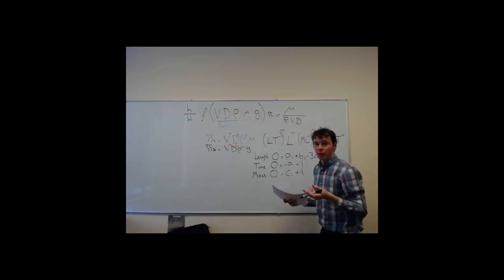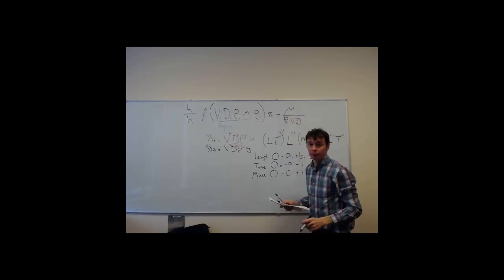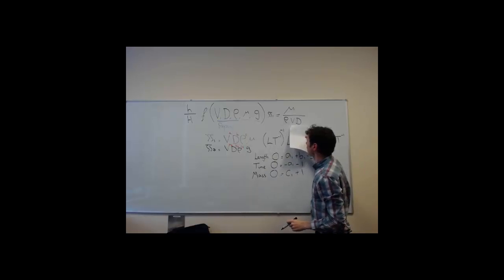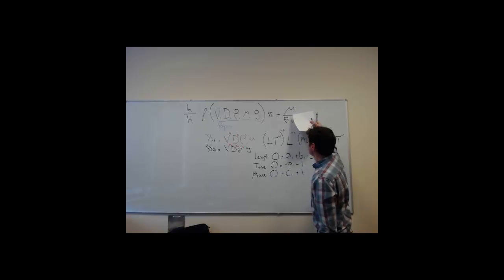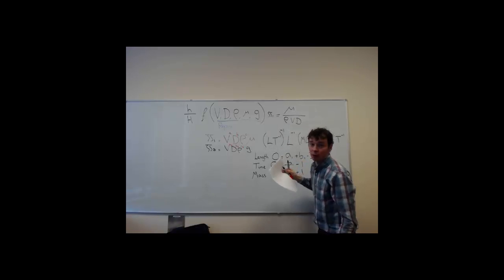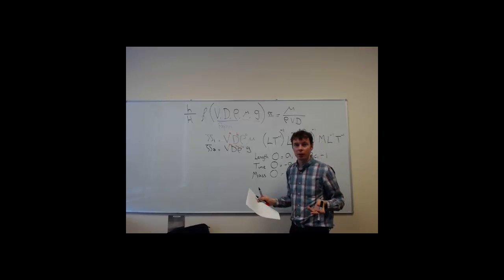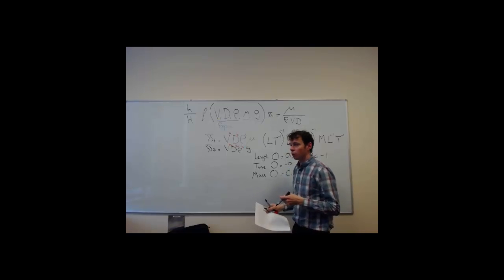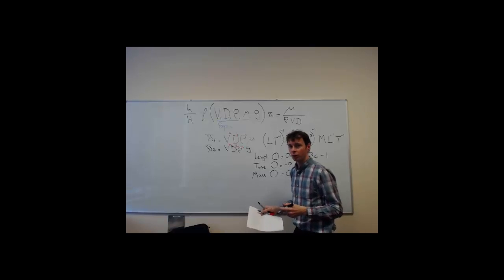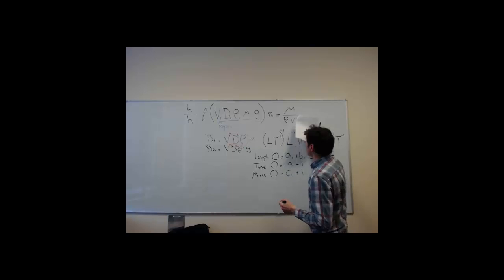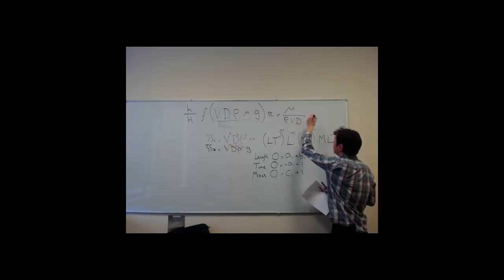Now, the interesting thing with dimensionless groups in Buckingham Pi is that you can manipulate the groups to a certain extent. You can probably see that is the inverse of the Reynolds number. Because the dimensions in the numerator and denominator are identical, we can flip it around. If you ask me for a unit of length on a construction site, and I said it was 1 divided by 43 meters, you'd think I was very strange and awkward. So this is effectively 1 over the Reynolds number, which is not of great use, but we can invert that quite easily.